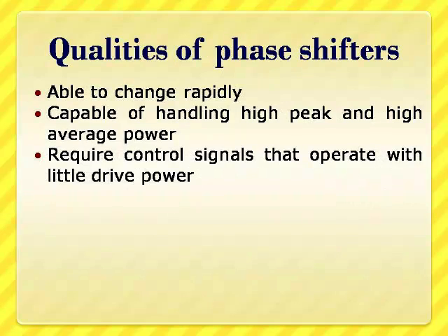But this practice is not common. Changing the velocity is directly possible by another technique. So this is accomplished by changing the broad dimension of the waveguide, and hence the phase velocity of the signal traveling through this waveguide.